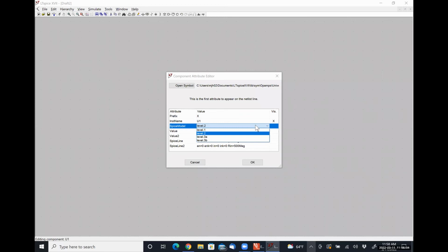Huh. We also have level 3, level 1, and level 3 has other op amps. So like universal op amp 3. Oh, okay. Well, then apparently I need to update. Well, what I was going to say, we're going to use level 2 in this class anyway, okay, for the overwhelming majority of stuff. Apparently, I will need to update LT SPICE after 3 years finally. But the other levels, which I guess correspond to other op amps for you guys, have editable parameters. So right here, the first thing that we could edit is AVOL, the open loop gain.